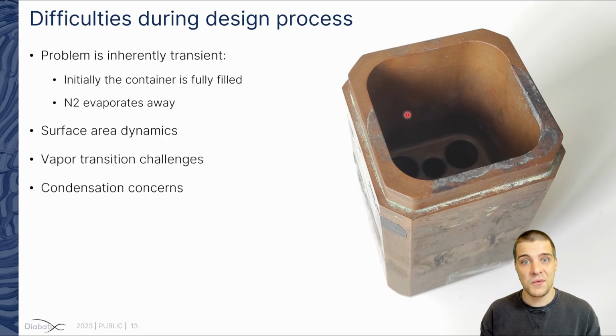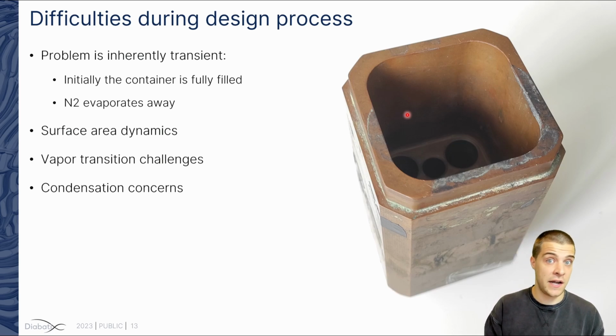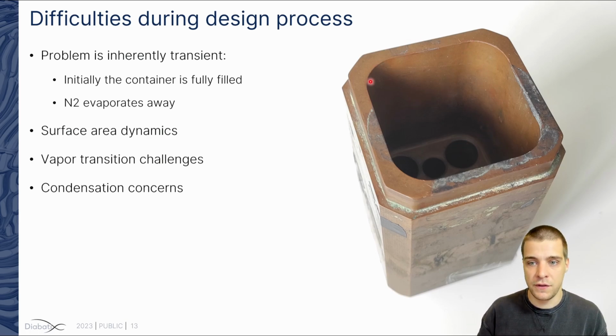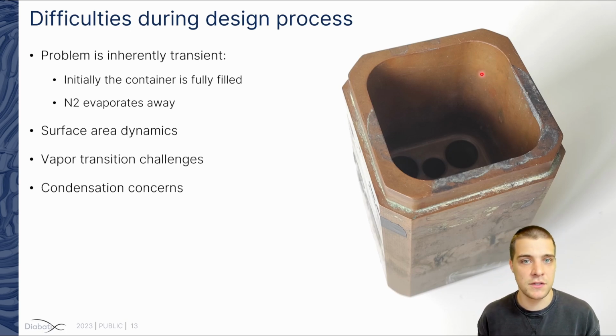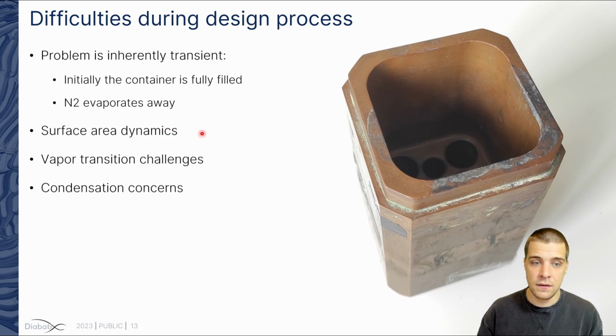There are quite a number of difficulties during the design process itself. First of all, the problem is inherently transient. The cooling solution starts with a fully filled container, but the liquid nitrogen evaporates away. As with any cooling solution, in general, the more surface area that you have, the better the cooling performance.